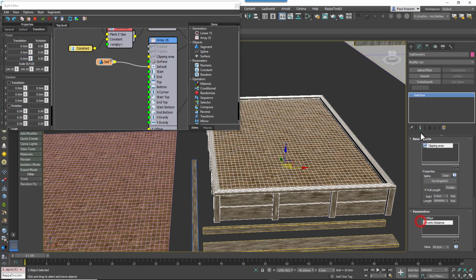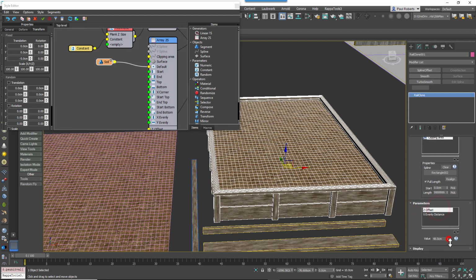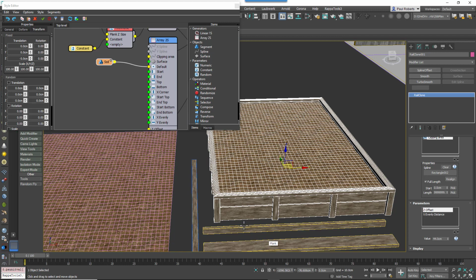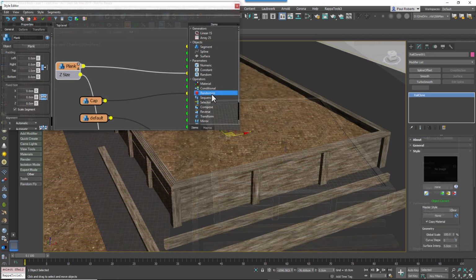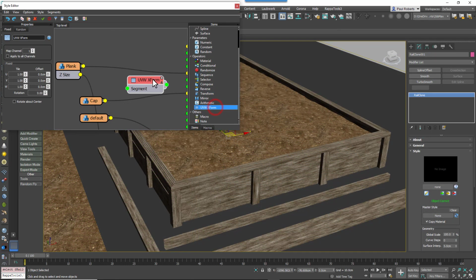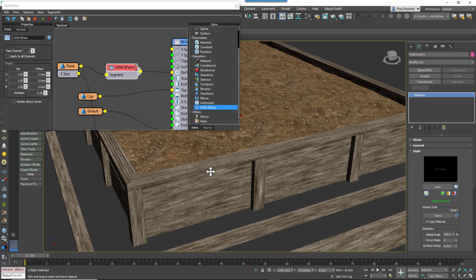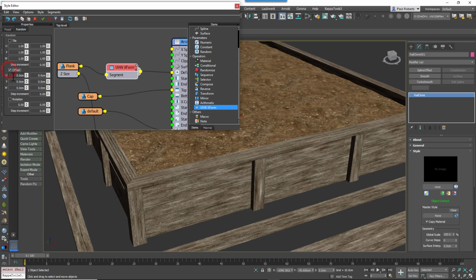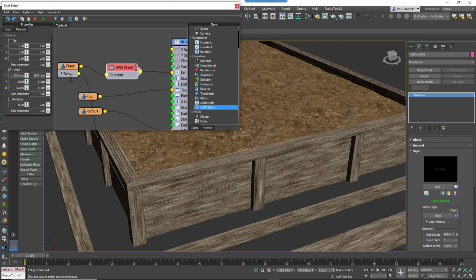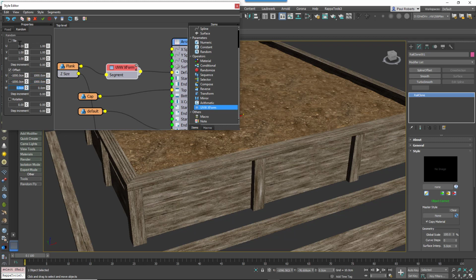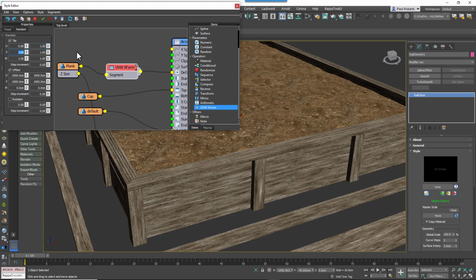So finally, we'll randomize the materials. At present, the material repetition is quite obvious. We can fix that by randomizing the offset of the UVs and adding some tint using RailClone Color. So wire a UVWX4 modifier between the wood segments. Go to the Random tab and in its settings enable offset. Enter a value of something like -1000 centimeters to 1000 centimeters for the U and V axes. You could also add a little tile variation while you're here too, if you like.